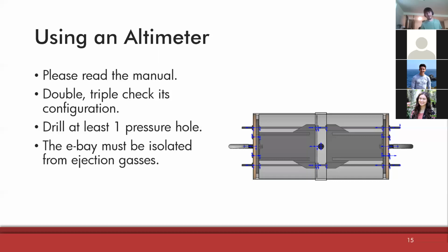It's a pretty easy way to do when you're building your rocket. If you want to get fancy and do something like this year's rocket with the twist to install, you totally can, but that's a lot more effort. I know one of the mistakes that we did make on that first year's rocket was we didn't do anything to isolate from ejection gases.